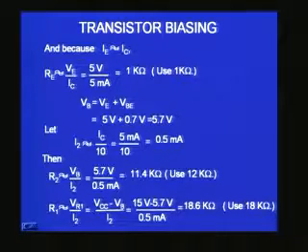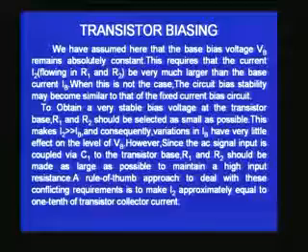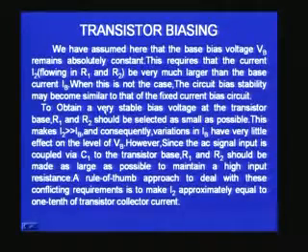So with this you can see that we have decided what will be the values of the various currents IB, IC, IE, and we have also found all the different voltages, and all the different resistors R1, R2, RC and RE. Therefore we have completely designed the voltage divider bias with the emitter current biasing. Right. Now I already mentioned to you that IB should be very small compared to I2. This is a very important condition, then only the transistor biasing will be stable. The stability of the biasing is a very important consideration.